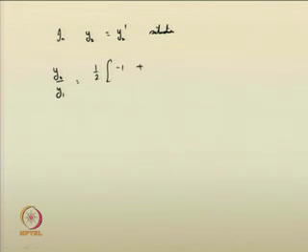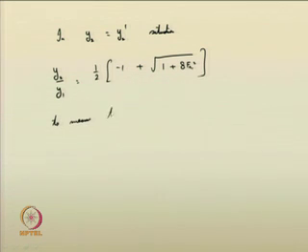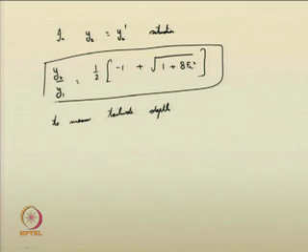So, you can use the sequent depth ratio relationship with FR1 squared to measure the tailwater depth. The tailwater depth is easily obtained from this particular sequent depth ratio, and therefore, you can design it appropriately.